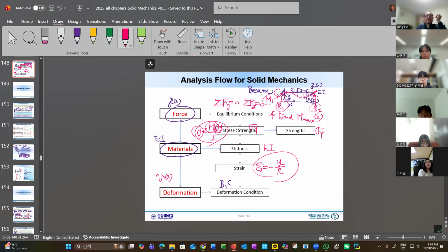And then, of course, the maximum stress will occur at the top or bottom, right? So once we have a location, say a certain point here, where the moment is maximum, then the stress will be like this. This will be the top and bottom, with maximum tension and maximum compression. So this stress should be less than yield strength. This is the very typical procedure of design.